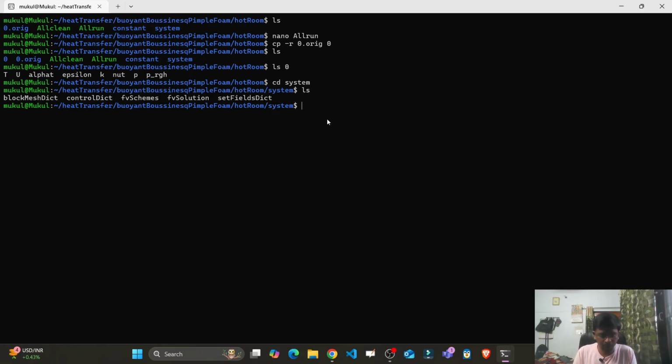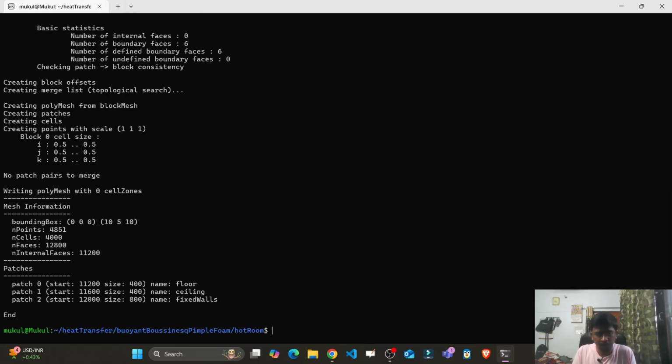Okay, so let's run that. So first we will go back, we are in the hotRoom directory, then we will run blockMesh. Mesh has been made. I will again clear the terminal.